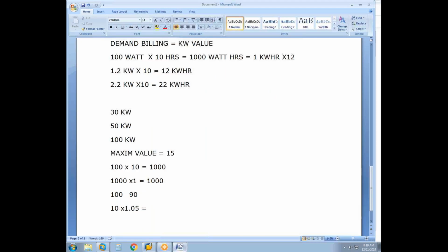But in industrial application, the reactive energy may be very high. So in certain countries, they put a regulation. If the reactive component is more than 15%, you must put two registers. One is showing the active register, one is the reactive energy, and both we are billing. That means the company cannot lose the money if the machine is holding back some current, which is unavoidable. We have to bill the consumer for both.